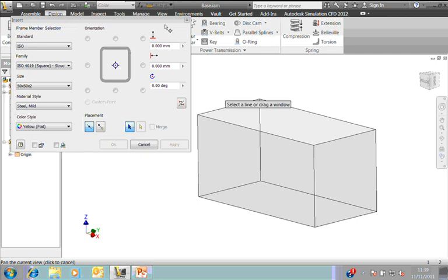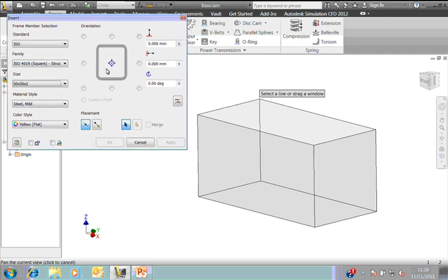Okay, now for the box section, I'm going to use the center to align with all the edges on the skeleton. I'll do that very quickly, but just as a tip really, if you're adding other sections, C-sections, beams and so on, then select the one edge first and place the section, and then get the alignment right by clicking on the relevant buttons here to align it correctly. And then always move off from one end to a line that connects to the edge that you just selected, and just move around and select individually to lines that are linked to the beam that you just selected. The way that works then is it uses the alignment of the first edge to sort out the alignment on the second and third edges that you select.